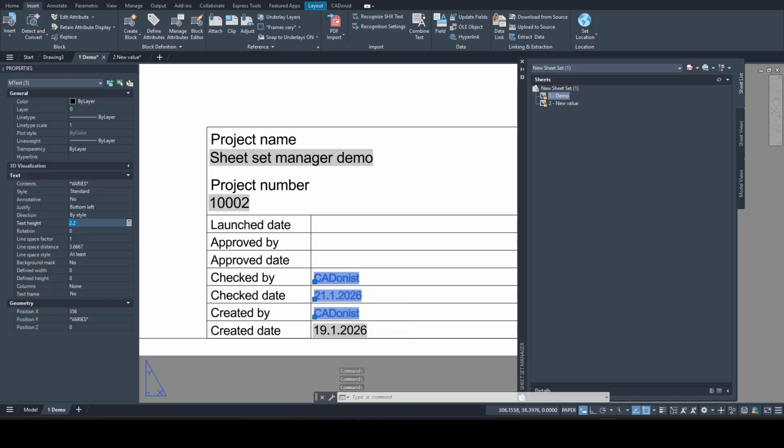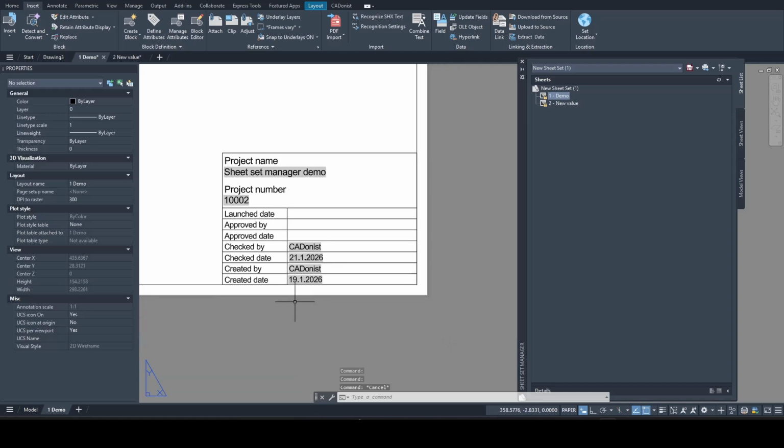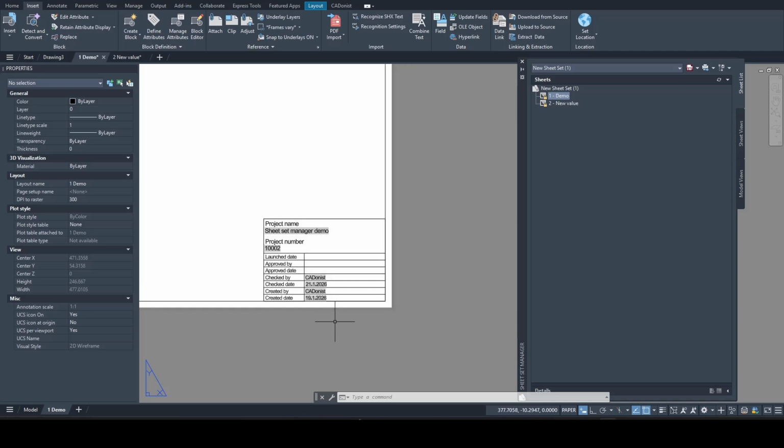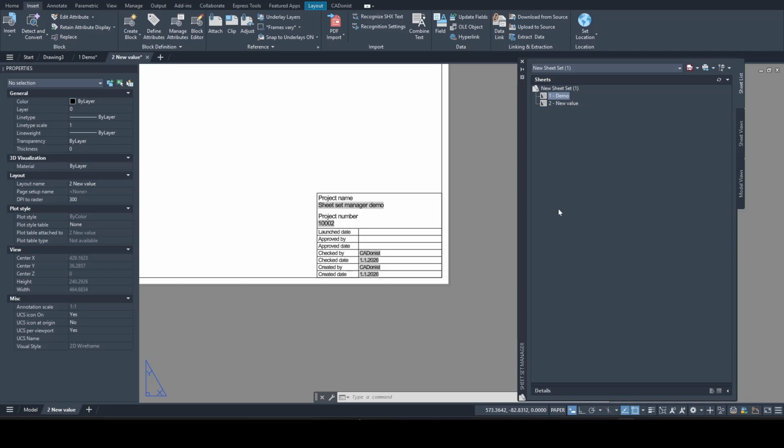So always keep in mind that simply replacing or updating a template will not update drawings that were created using an earlier version of that template. This is a common source of frustration, especially for Plant 3D users. Plant 3D works on the same principle. Content is taken from a template, isometrics are generated, but any later changes to the template will not affect already created isometrics. To apply those changes, the isometrics must be deleted and again recreated.